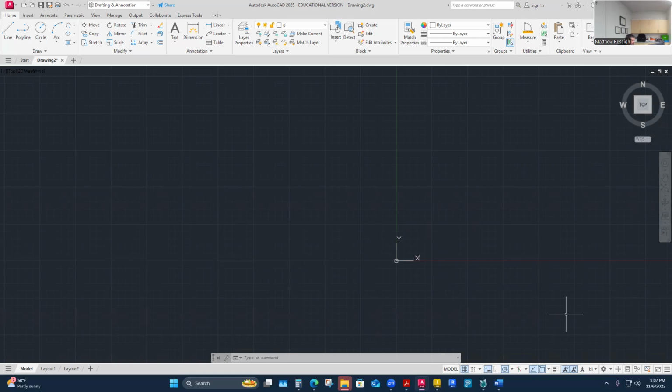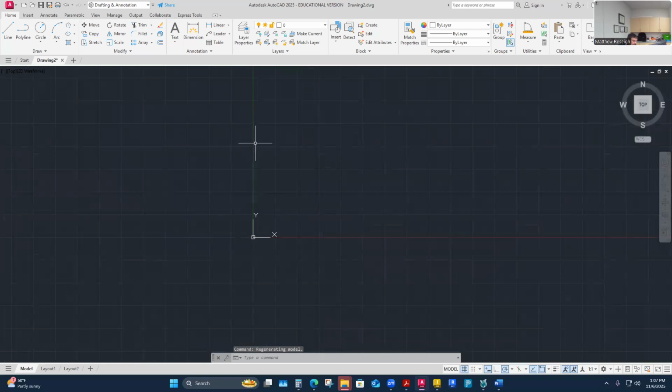They'll have different line types and colors as I make them. But I don't really want to draw with the line weight turned on. It gets a little bit confusing looking because you'll get thicker and thinner lines. We want it to print that way, but we don't usually draw with the line weights turned on. It feels odd. You won't know that till you actually try it, and maybe we can mess around with it. But okay, so that's that side of the status bar.